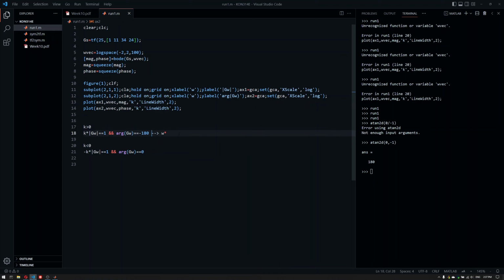Because we have two simultaneous conditions, what we need to evaluate is at which frequency the system has negative 180 degrees phase or 0 phase. Both of these points are going to be critical points, and we're going to plug that frequency into the first condition and look if we can satisfy them both.